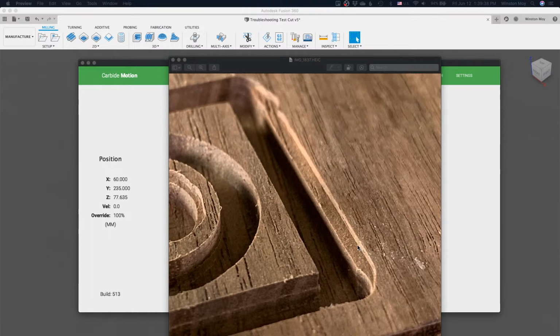If you don't zero perfectly, your first layer can sometimes be a little shallower than the subsequent cuts. Because of that, you have less force, and so the spindle settles in a location halfway between where the backlash wants it to be and where the material is pushing the spindle to be. So sometimes you get different layer lines on the first step down, because the cutting forces the machine is soaking up are different as it cuts deeper.